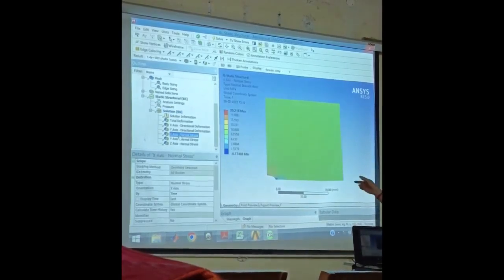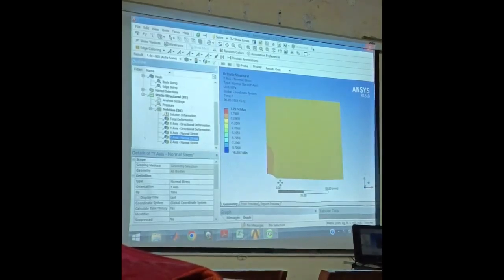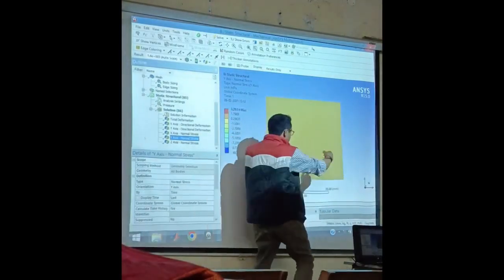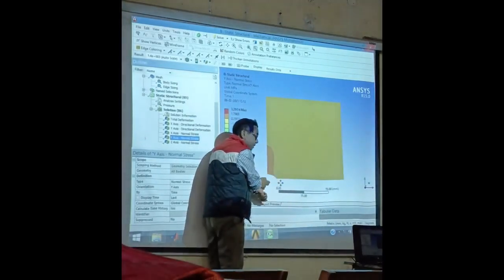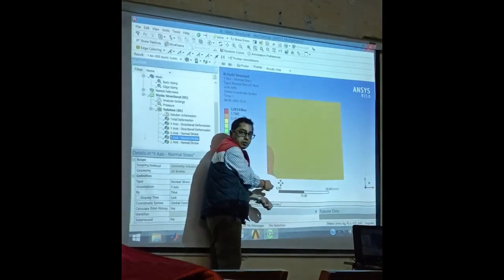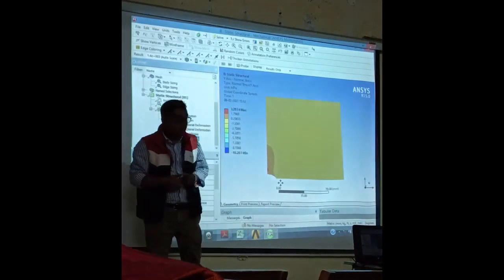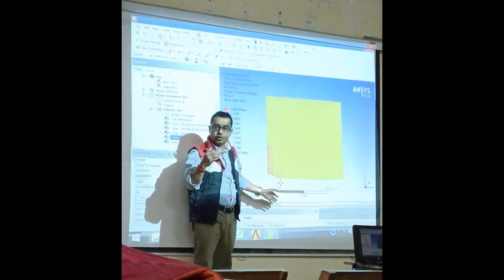It is 20, now it is 20.218. K is 2. Now this is once again minus 10. So compressive was same. Now the question is why I have applied the load in these directions. Now when this is an ellipse looking like this, the stress concentration factor is more. But when I am here like this, the stress concentration factor is less. Why? Because this is the effective area giving resistance against the load.